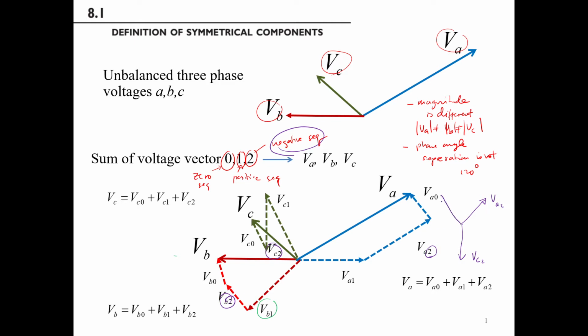So this is VB2. From this picture, if you rotate this in the same idea, we rotate this counterclockwise and we stand at this point. You can see that phase A just enters first, so A first, followed by C, and then followed by B. So the sequence in which the phase voltages enter is in the ACB sequence. So this sequence ACB is called negative sequence.